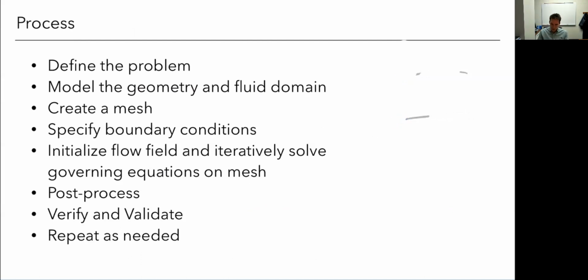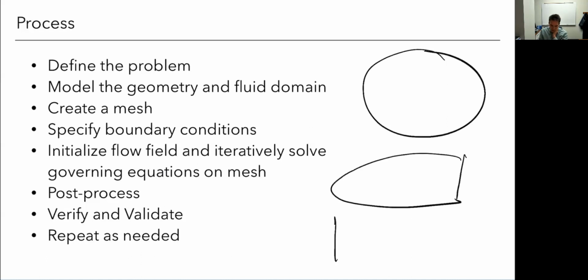I also have to think about the domain. As I mentioned in some tutorial videos, there are different types of shapes. Sometimes we use a circular shape. Sometimes it's like a bullet shape. Sometimes a rectangular shape. Those are some of the most common. The best practice guide of the software you're using will have some suggestions on whether it's subsonic or supersonic or whatever. But in all cases, we need the boundary to be far away.